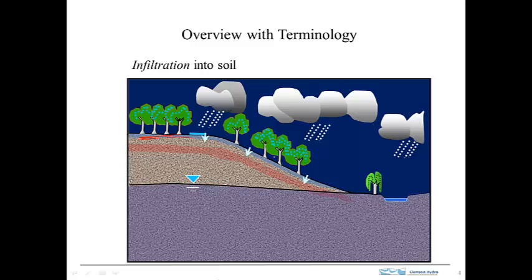That happens fairly early in the rainfall, and then with continued rain, this zone above the B horizon increases in saturation, and the water is moving downward. It reaches this lower permeability zone, the B horizon, and that causes the saturation to increase, and that gives rise to downslope flow.